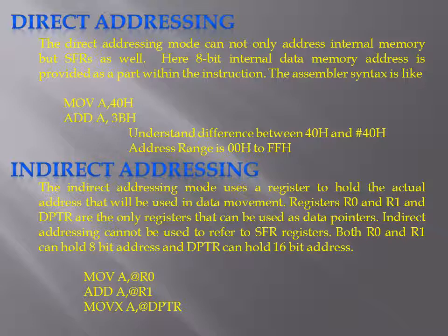In the same way, ADD A, @R1 means R1 will be taken as the pointer. It will point towards a memory, and that memory data will be added to the contents of the accumulator.